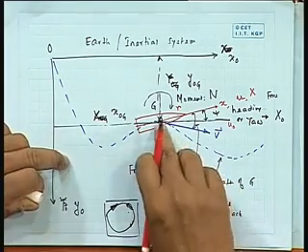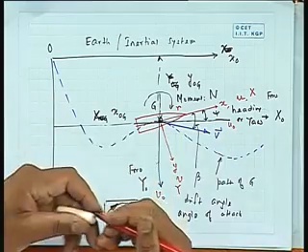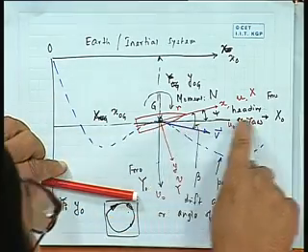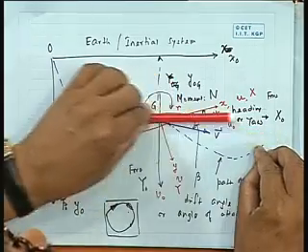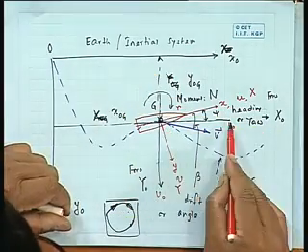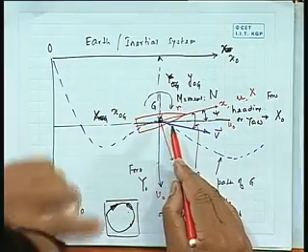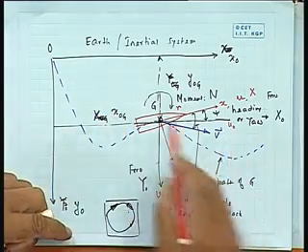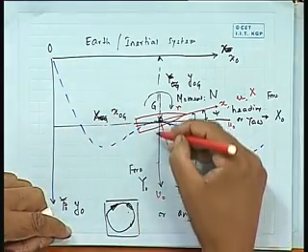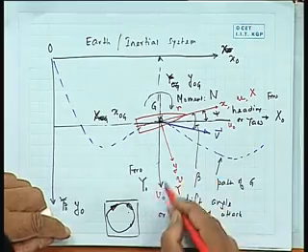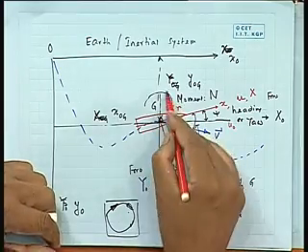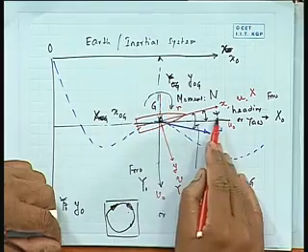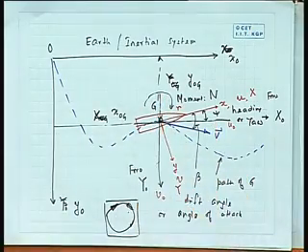Again, we go slowly. Along the earth axis, I have a velocity u dot, which is equal to x_og dot, the d by dt of x_og. I have a velocity v0, which is y_og dot, and a rotation which is psi dot, which I am calling r.